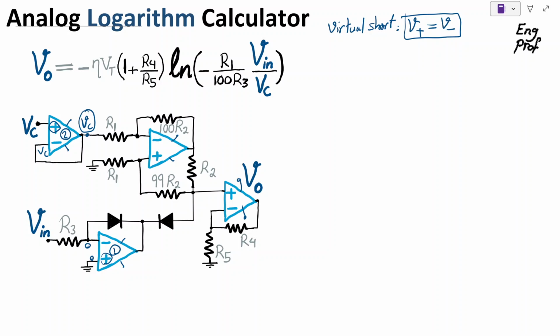I'm going to show you that this second stage here with op-amp 3 is just working as a current source, and it will inject a current through the circuit which we refer to as I2, and that's going to simplify the whole process. That current cannot go through the positive input terminal of ideal op-amp number 4 because it has infinite input impedance. So all the current that is coming out goes through the lower branch downward toward diode number 2, resulting in a voltage drop VD2.